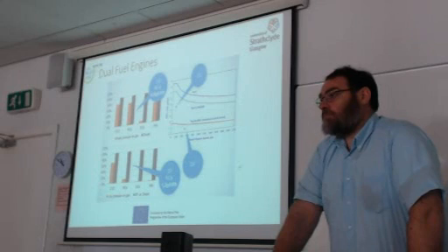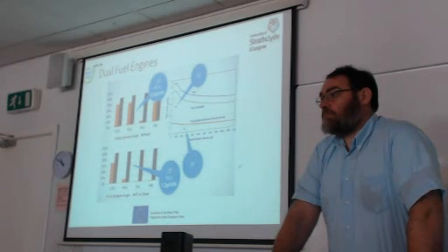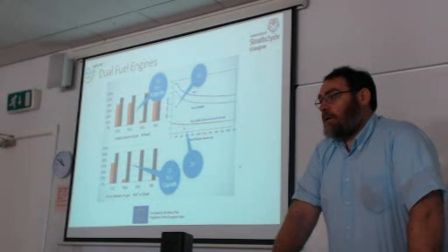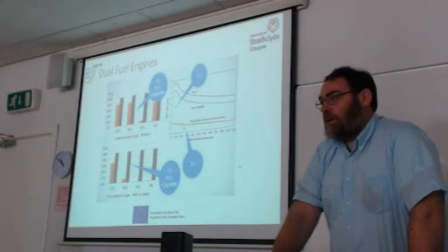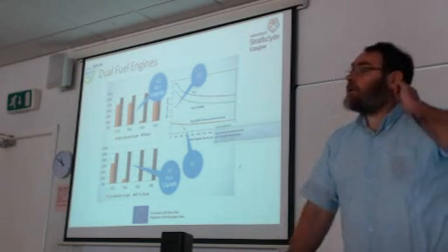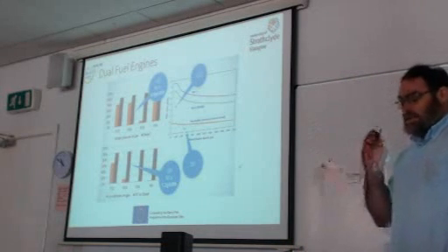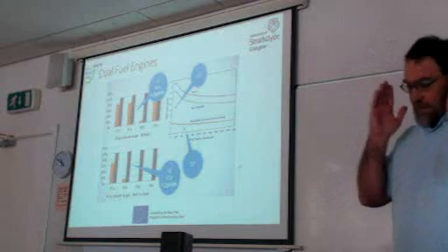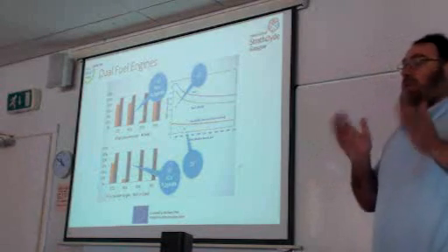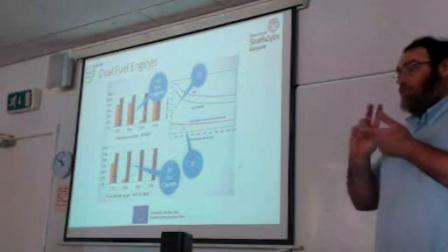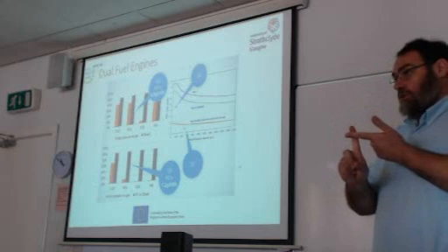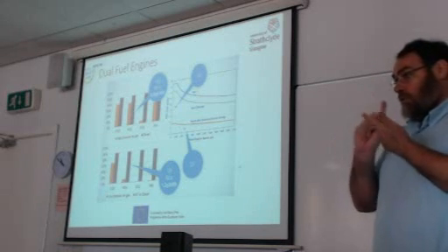But now you said the Wärtsilä engine uses a two-stroke engine. No, I said both. Wärtsilä engine, yes, but they still use low pressure compared to MAN B&W. The MAN B&W engine uses up to 300 bar for injecting the fuel, but in your slide, the Wärtsilä two-stroke engine uses only 10 bar. Correct. So is there a performance difference? Yes, I mentioned that there is a decrease of delivered power. So the Wärtsilä two-stroke engine's performance is similar to four-stroke dual fuel engines?